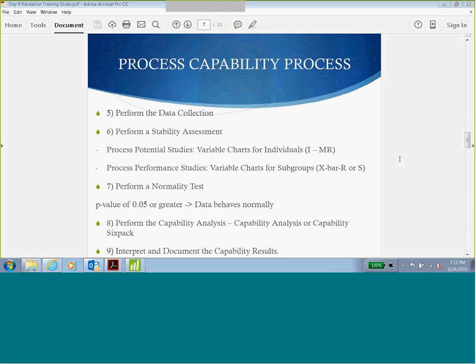What you're going to be doing is you're going to have set your upper specification and your lower specification limits. So that is fixed. That is not going to be changing at all. You're just going to be changing the sample information, the measurement results. So by changing the measurement results, for one result set you should be getting a Cpk of greater than 1, and by changing the other results you'll be getting a Cpk less than 1. So do not change the specification limits.